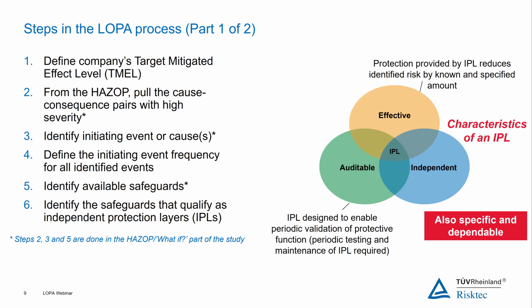You have documents from the UK HSE, like the Process Safety Leadership Group, that'll have specific suggestions for it. And often you'll find this TMEL, as it's called, will be different for employees and members of the public as well. So especially for onshore facilities, it may be that the TMEL will actually be more stringent on members of the public than it will be for the specific employees.